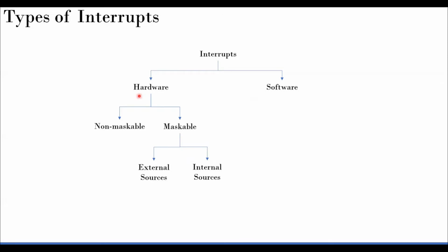On the other hand, for hardware interrupts, there are two types typically, non-maskable and maskable. Non-maskable means they are really high priority interrupts and you cannot do anything to mask them. They will always be running. Something like, nowadays, even temperature rise in a system is non-maskable because it goes beyond a certain limit. You just need to restart. There is nothing that you can do. So they are non-maskable. The CPU cannot mask them. They will always be there. But then there are maskable interrupts where the CPU can mask them. So even if it happens, just ignore it. But they are also important. But most of the time, there is a provision to mask them.